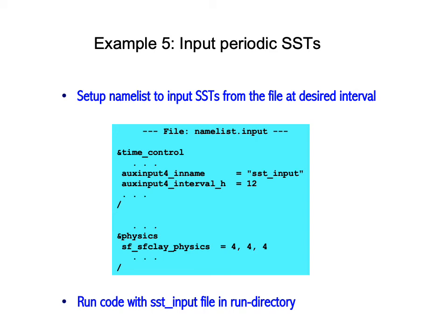An important thing to notice is how the data got into the WRF model. Exactly the same way that we did not have to worry about how the all-moist variable was going to be specifically output, we do not have to worry about modifying the WRF source code to bring in this brand new variable. We're not going to say inside of this example how that field is constructed, though you could use the real program to do it. That's exactly how we bring in the SST update data for the WRF model currently.